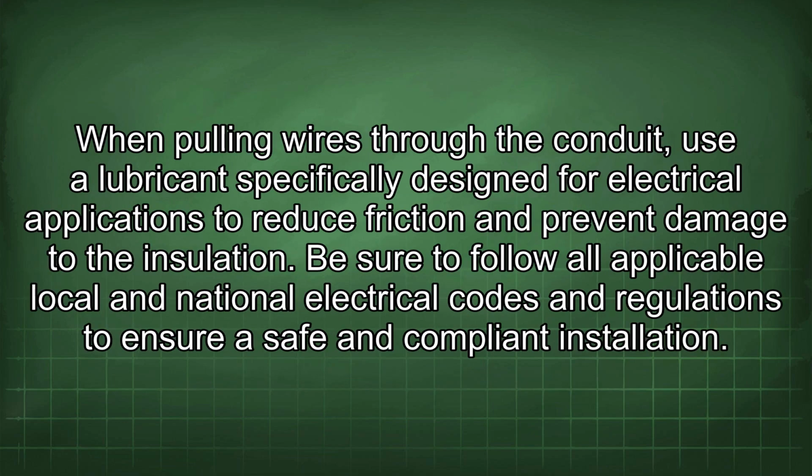When pulling wires through the conduit, use a lubricant specifically designed for electrical applications to reduce friction and prevent damage to the insulation. Be sure to follow all applicable local and national electrical codes and regulations to ensure safe and compliant installation.